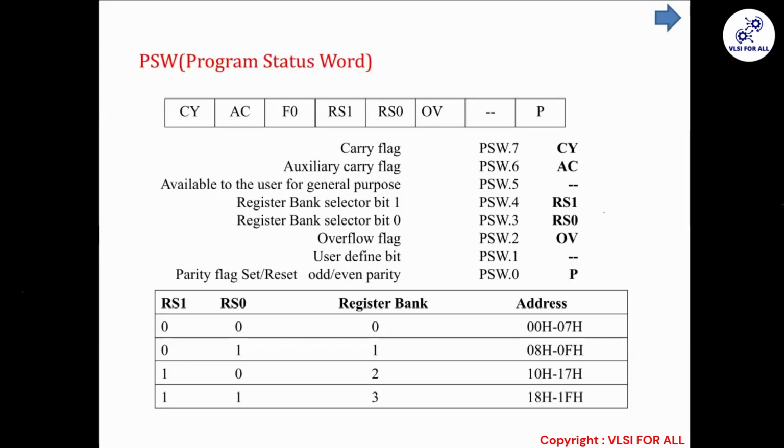In the fourth one, it was 1 plus 1 plus 1, and it gave me one carry, which I have to carry further. Yes, ma'am, that is auxiliary carry, which is happening. And so carry is also generated in this operation as well as auxiliary carry. Is it right? Yes, ma'am. Two flags will be set high in this case, carry and auxiliary carry.